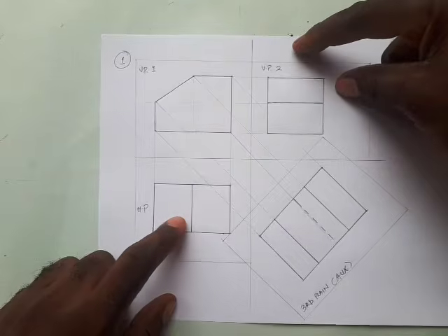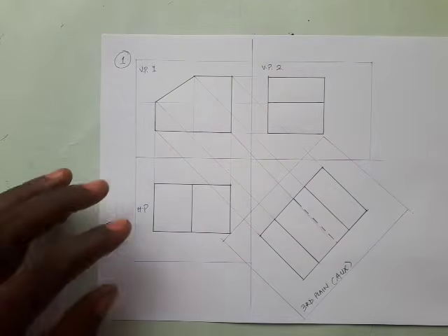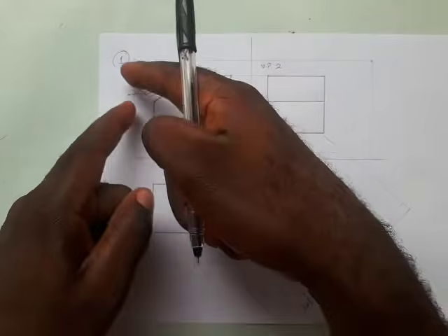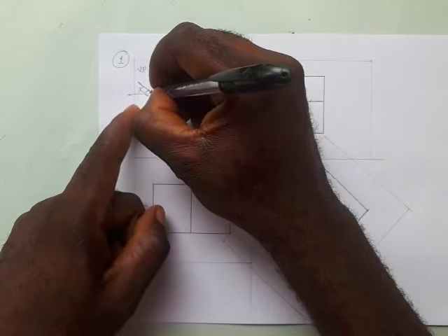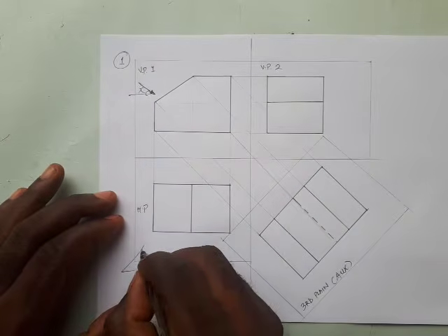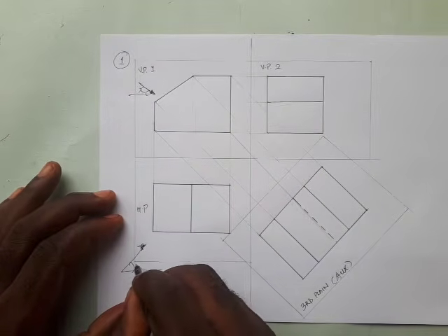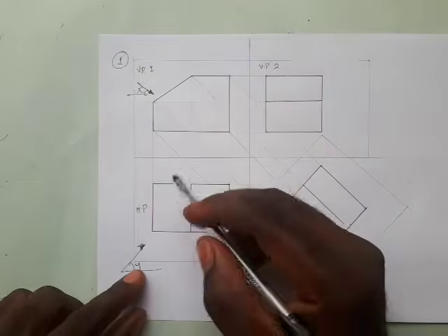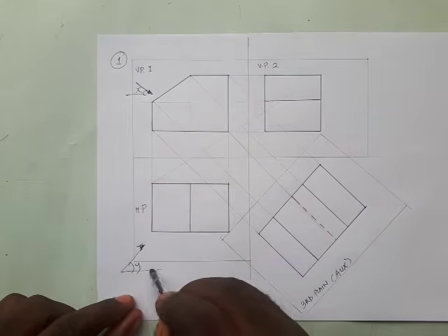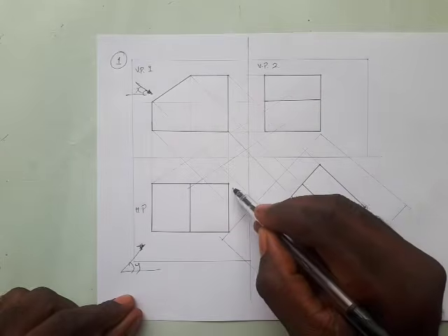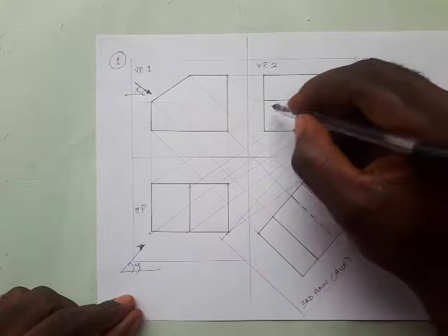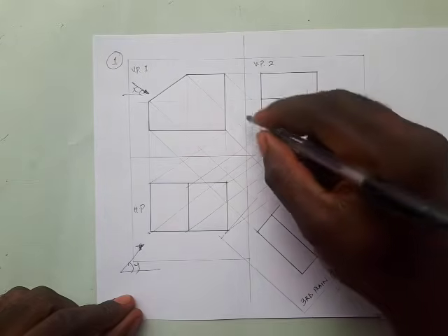Now, ordinary plan will give you an auxiliary elevation. So for example, remember this is projected at an angle, let's say angle X. That is why these lines are moving in this direction. This is the arrow. Now, if I'm to project at an angle here, let's say angle Y, I'm going to draw lines perpendicular, at angle Y in this form, and draw a line perpendicular to it, which is my XX line, and project.